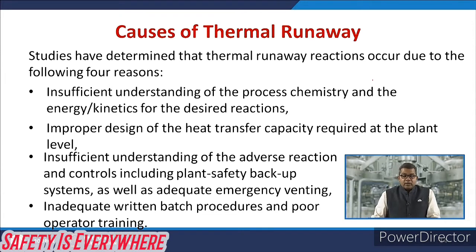Now there may be several causes for the thermal runaway. Studies have determined that thermal runaway reactions occur due to various reasons, and we have listed 4 reasons. Sometimes there is insufficient understanding of the process chemistry and the energy kinetics of the desired reaction. That means sometimes you may negate the effect of exothermicity. Sometimes it may lead to improper design of the heat transfer capacity required for the plant.